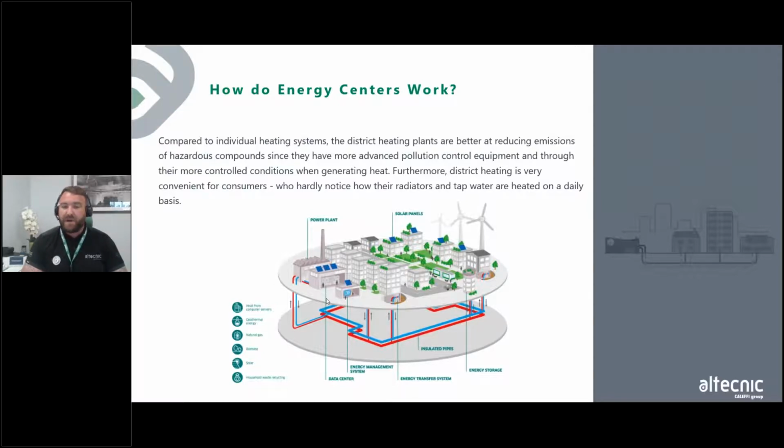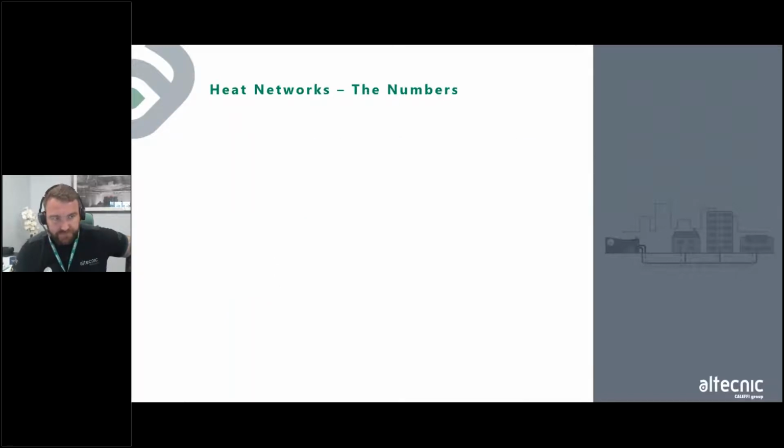So that diversity factor is critical when people are sizing these systems, to make sure it's right. If only 2 or 3 people move into a development that's been designed for 200 people, obviously there's going to be an impact on that as well, because there isn't that huge demand on the system itself. So it's very important that we size correctly, using the right diversity factor.